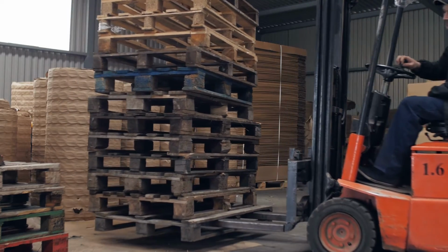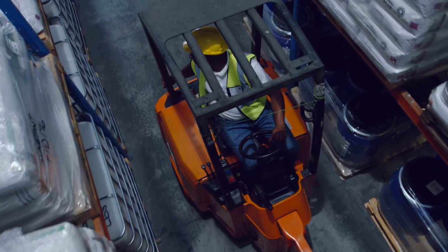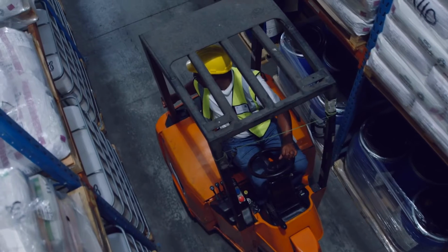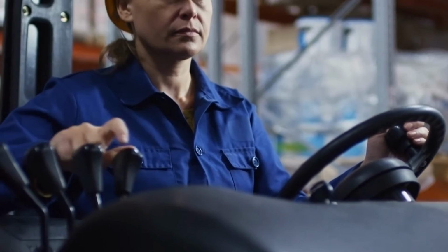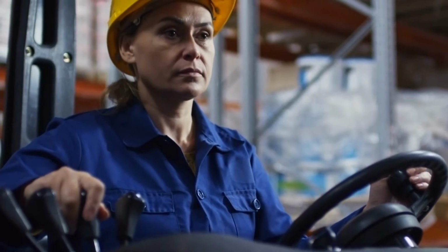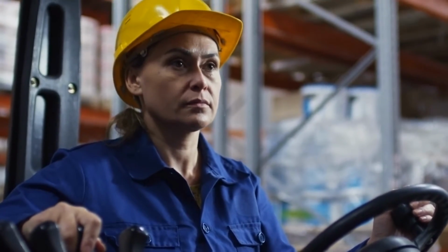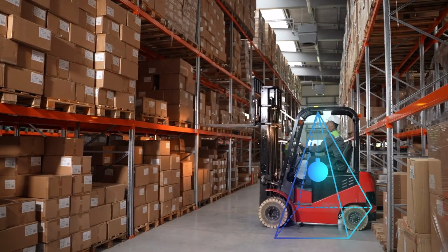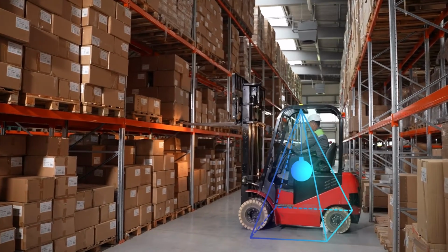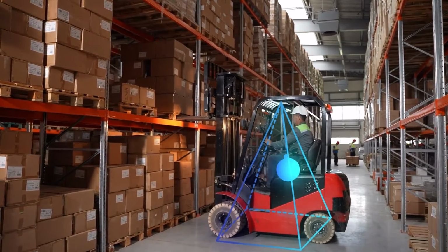While the concept of the stability triangle explains stability on a two-dimensional level, forklift stability also involves a third dimension, transforming the concept into what we call the stability pyramid. This three-dimensional concept provides a more nuanced understanding of forklift stability and accounts for its height. Imagine the center of gravity as a ball hanging from the top of the pyramid. Depending on the height of the load, the shape of the pyramid then changes.